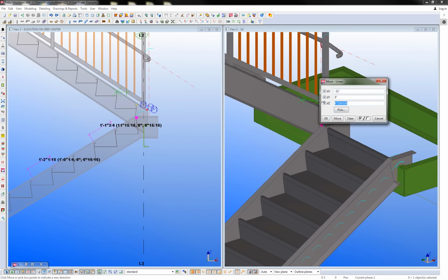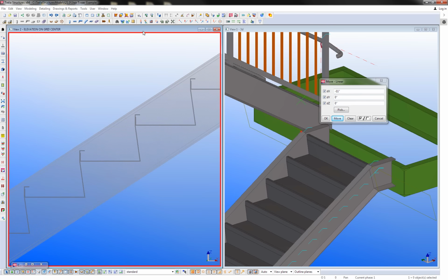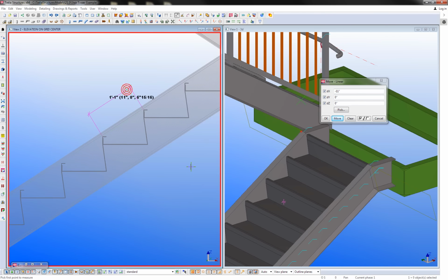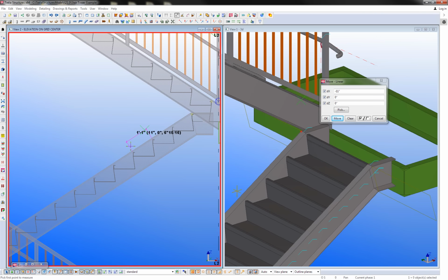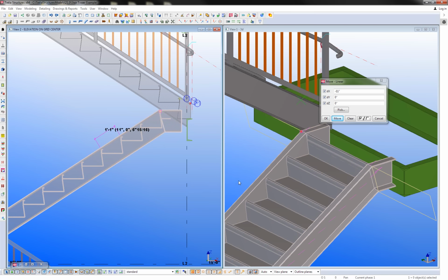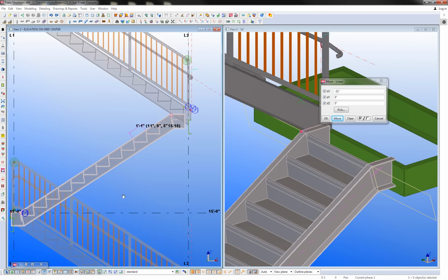If it's not coming out to exactly 11, that's when the move linear really comes in handy. In this instance, I've got it laid out to be perfectly 11 inches, so I could have just typed it in. So I'll go ahead and hit move again, pull that stair back, and let's go ahead and redraw my view and then redimension. I believe that's the correct point that I'm looking for. So if I measure these again, yep, so there's my 11-inch width and my 6 15/16 height. So like I said, all I had to do was grab that handle and just pull it back until I got to the right dimensional property. So you can adjust these on the fly like that pretty easily.